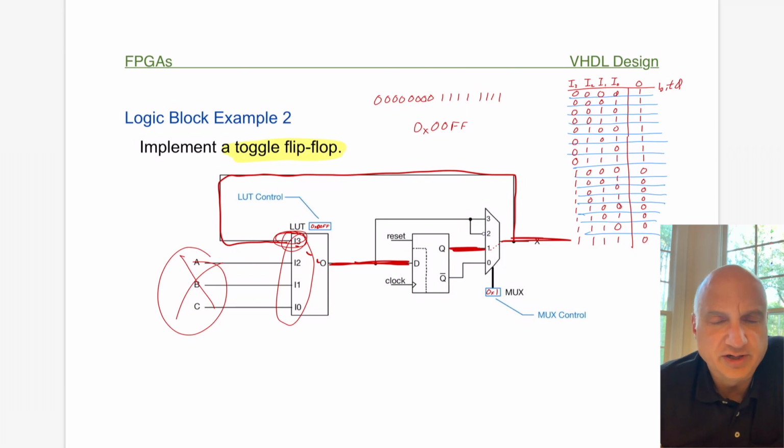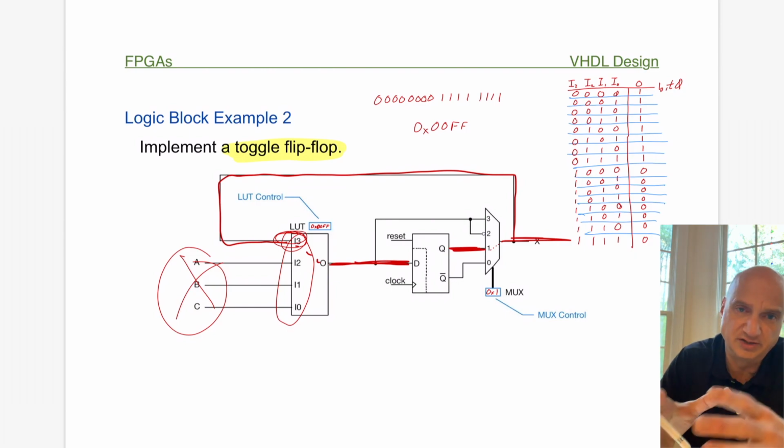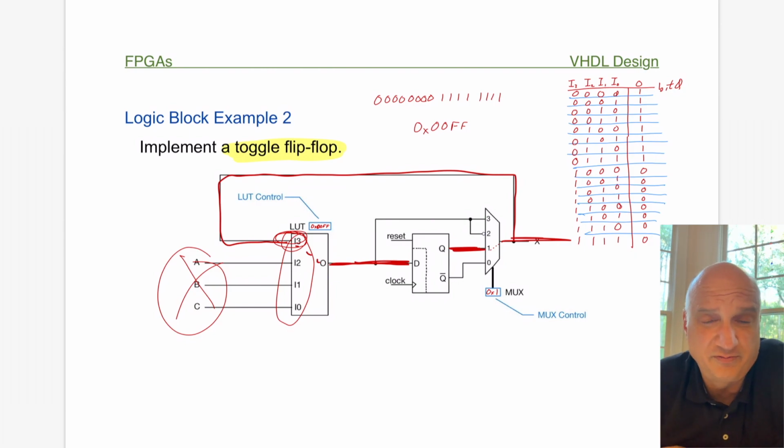Like I've said 100 times before though, you don't design based around particular hardware. You resort to these kinds of things if you're really trying as an engineer to fit your design into a particular device, and you're finding yourself running out of room. You can play games with this and at least scrape off some excess size and make it fit. And it might even affect your performance as well. So smaller LUT paths can result in higher frequency because you're not going through as much combinational logic. So there's lots of little tricks you can play.